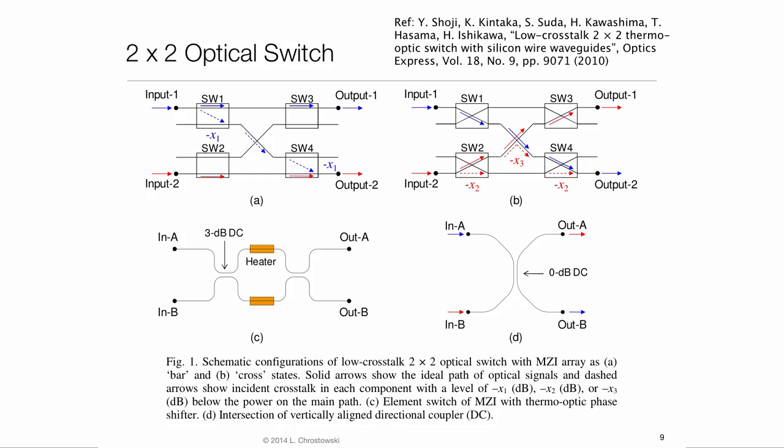Next, we discuss circuits that can be built using several of these thermo-optic switches. First, the thermo-optic switch can be built using directional couplers. The directional coupler, in the ideal case, acts as a 50-50 beam splitter and has 2 inputs and 2 outputs. This configuration is more versatile in that it allows one of the 2 inputs to be switched to one of the 2 outputs.